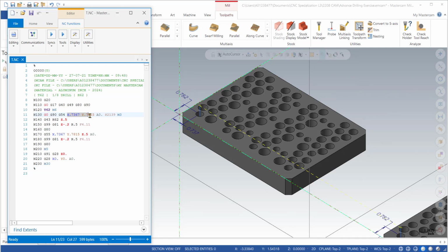All right. So if you look at the codes now, with G54 on part number 1, the coordinates we are getting as per our dimensions, and the same with G55, that's part number 2, we are getting the same coordinates. So basically, by changing work offsets, we can run both of these parts together.